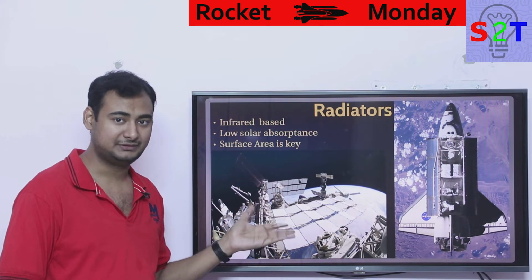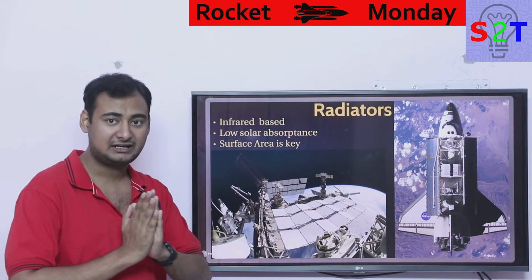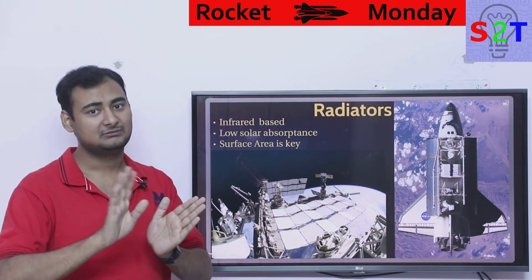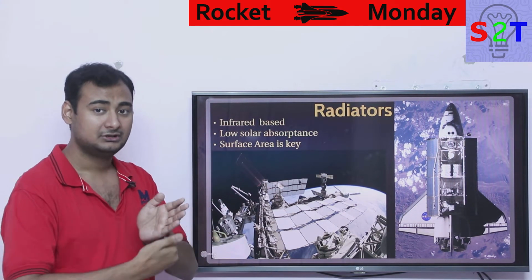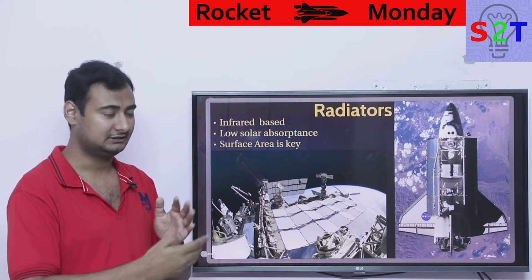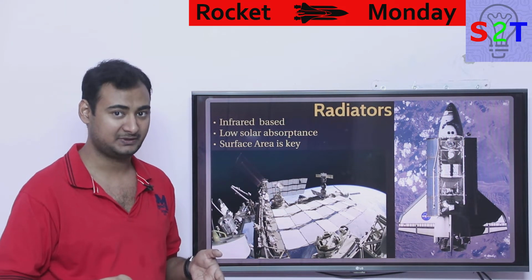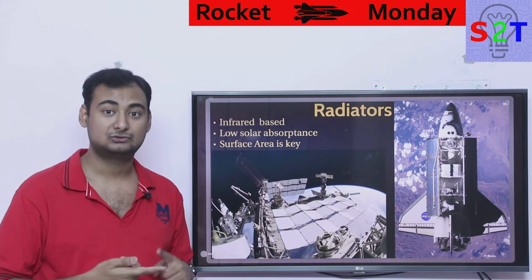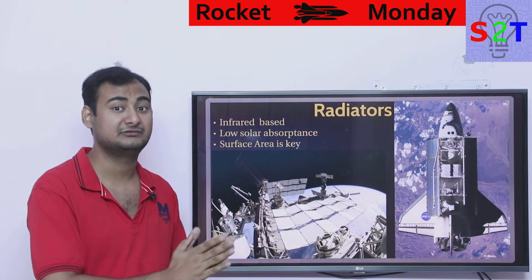So generally we have to make a compromise, because a radiator basically has 2 sides. The side that is facing the sun will be shut off. The side that is facing the night side, or shadow, will have a lot of coolant going through it and dumping its energy in the infrared spectrum. The coolant that is selected is chosen in such a way that it can dump most of its energy in the infrared spectrum.